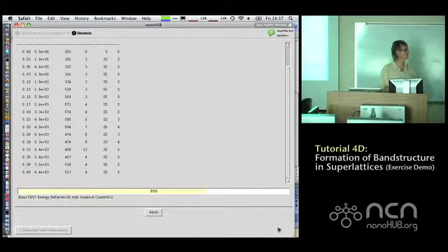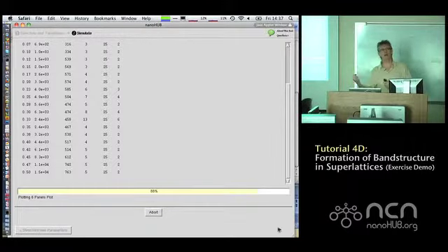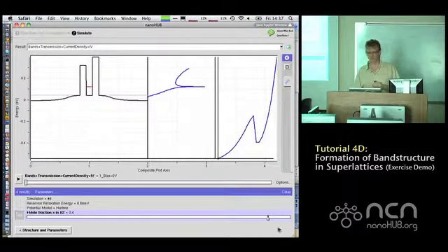No, current will be there. But think about it this way. You're pulling on the collector side, you're wanting to apply a voltage, and you want to pull this down. And the charge is piling up, it starts to float up. That means to get the peak current, I have to pull much harder down. So I have to apply a higher voltage to get the same peak current. So the whole curve will shift to higher voltages. What effectively happens is your whole IV curve leans over a little bit. It'll lean over and get linearized.